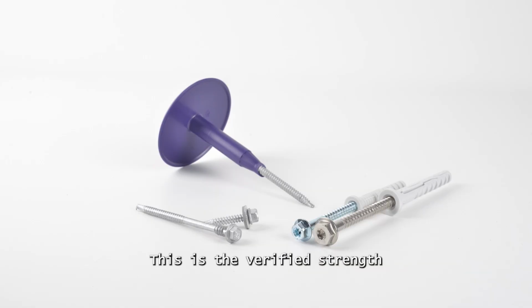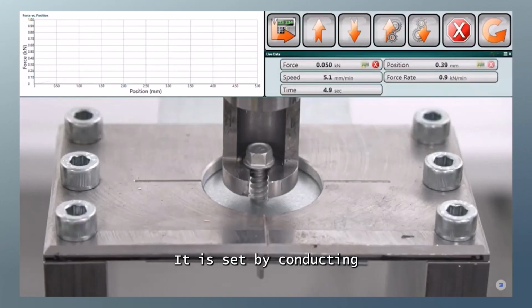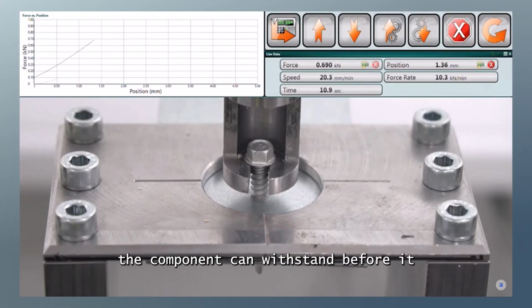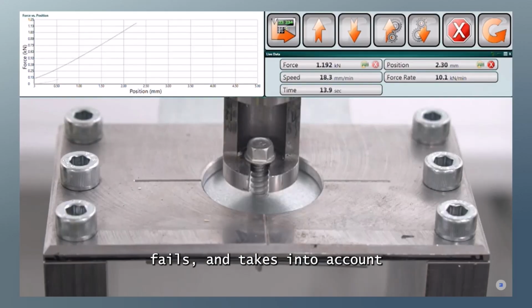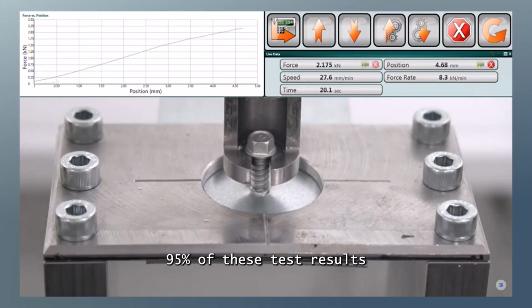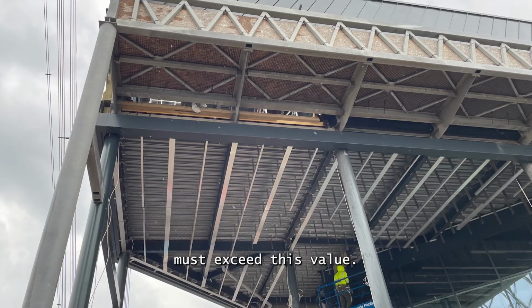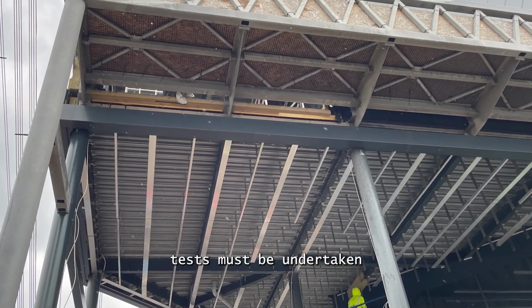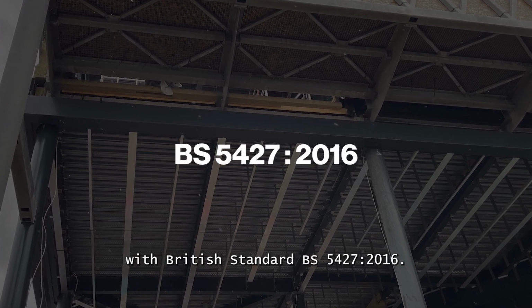Next, we have the characteristic load. This is the verified strength of a component such as a fastener or a fastener assembly. It is set by conducting tests that determine the ultimate load the component can withstand before it fails and takes into account the standard deviation of the test results. 95% of these test results must exceed this value. In the case of fasteners, tests must be undertaken in accordance with British Standard BS 5427 2016.